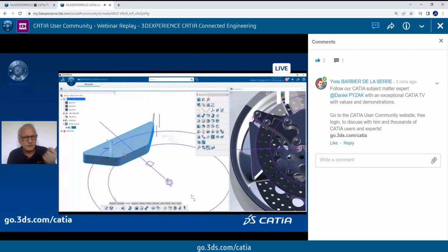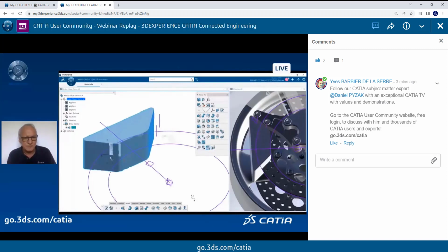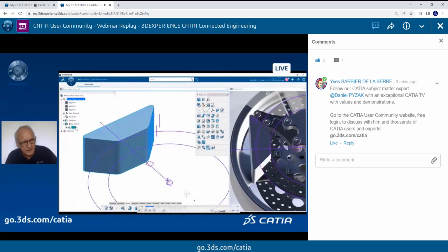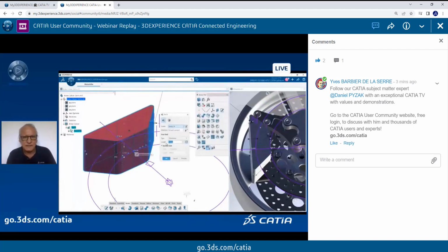And then I just need to select the direction of the extrusion and the value, the thickness of the pad. And I directly type in the command, and CATIA creates a feature pad in the spec tree. Okay? You could have done exactly the same with a traditional, let's say, CATIA V5 way, where you click on the command pad, you have a dialog box popping up, you enter values, and then the feature pad is aggregated in the spec tree. But here it's much faster. Here you see the pad dialog box that you can use if you want to advance more details in your pad feature.